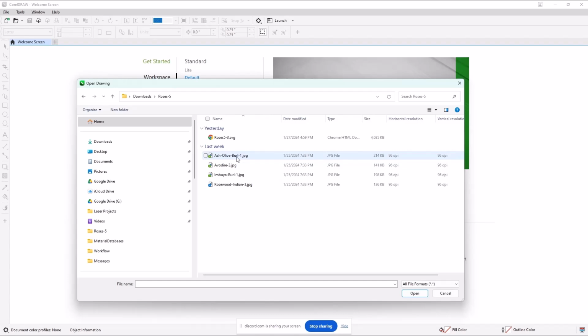Yeah, that's correct. And again, part of the reason for spending a few seconds up here is that if you have this menu bar, you're 90% guaranteed to be in the standard mode. But by clicking on the window tab before you load anything, you'll be able to see, like I said, on the drop down, what workspaces, if any, you have. And if it's defaulted to the standard one, quit while you're ahead. It's the right choice.